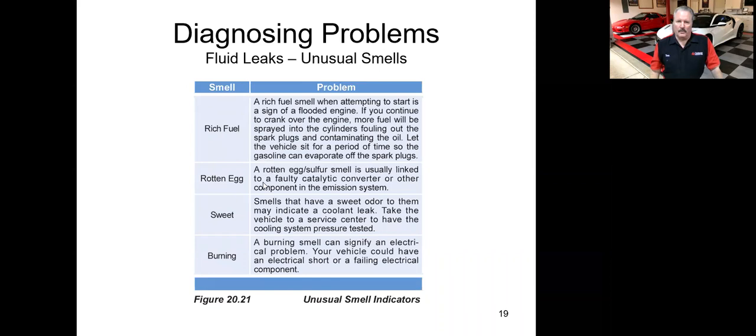Unusual smells. Well, you can smell rich fuel. A rotten egg smell means the catalytic converter is probably getting too much fuel, and it ends up smelling like rotten eggs. Here's a real common one.